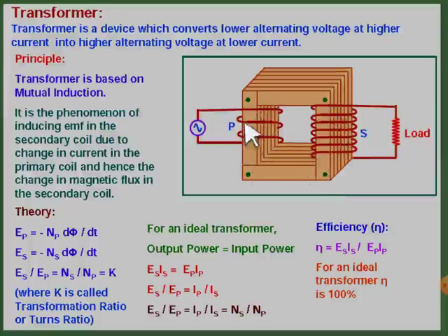If they are put one after the other, it will be just like a rectangular core. We make such sheets of L-shaped soft iron rectangular core so as to have less eddy current, because eddy current decreases the amount of electrical energy.